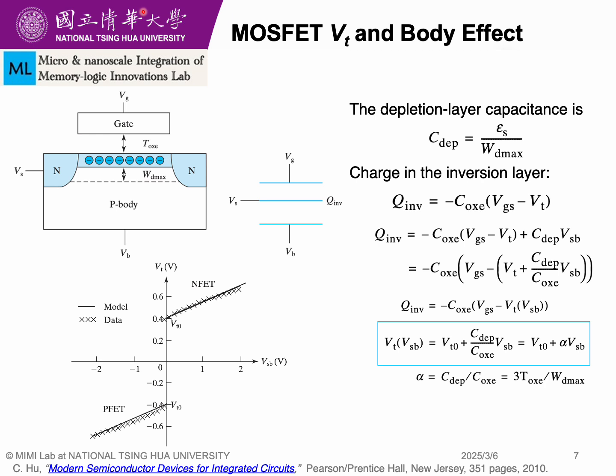Typically the inversion layer in the MOSFET acts like a thin resistive film that connects the source and drain, and this film at the source potential Vs forms a capacitor with the gate oxide as the dielectric. It also forms a capacitor with the body, with the depletion layer as the dielectric.